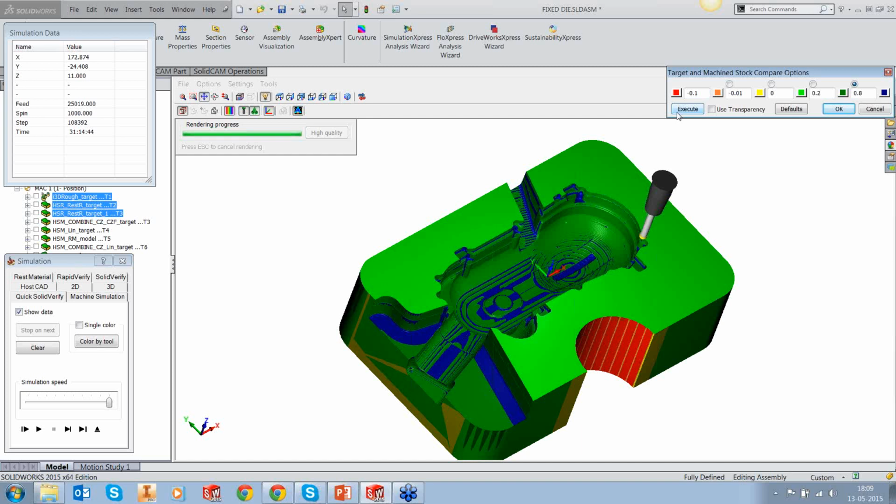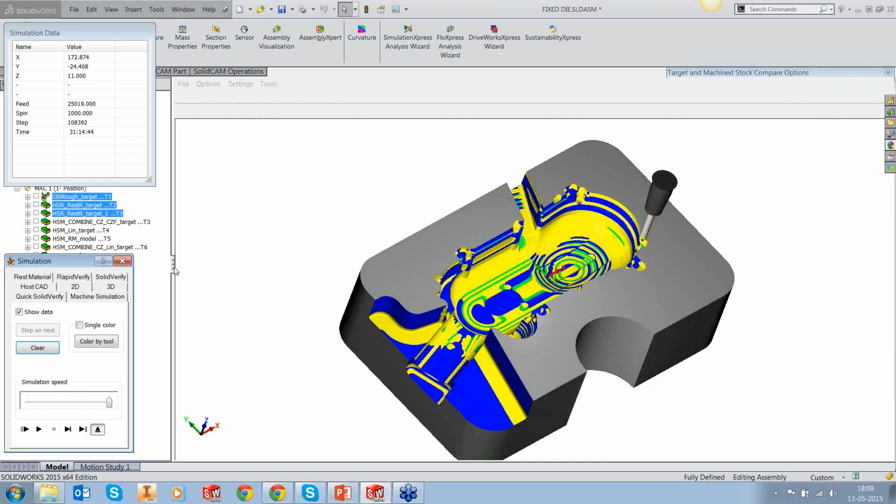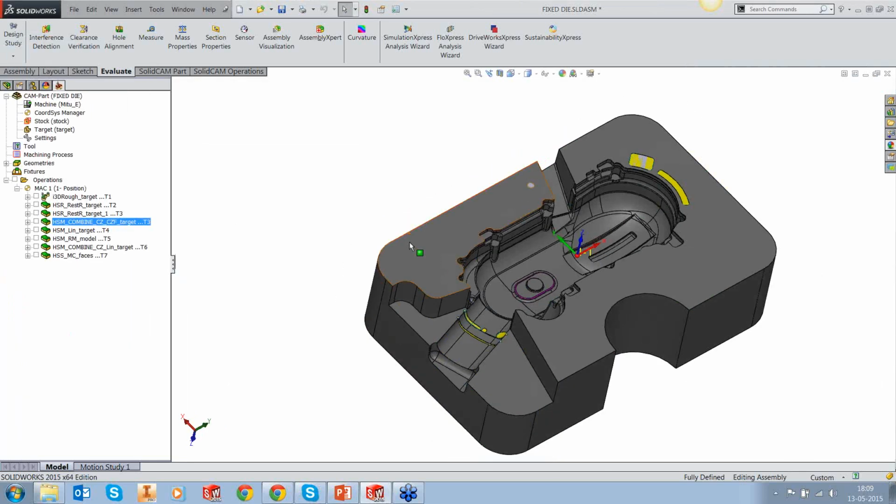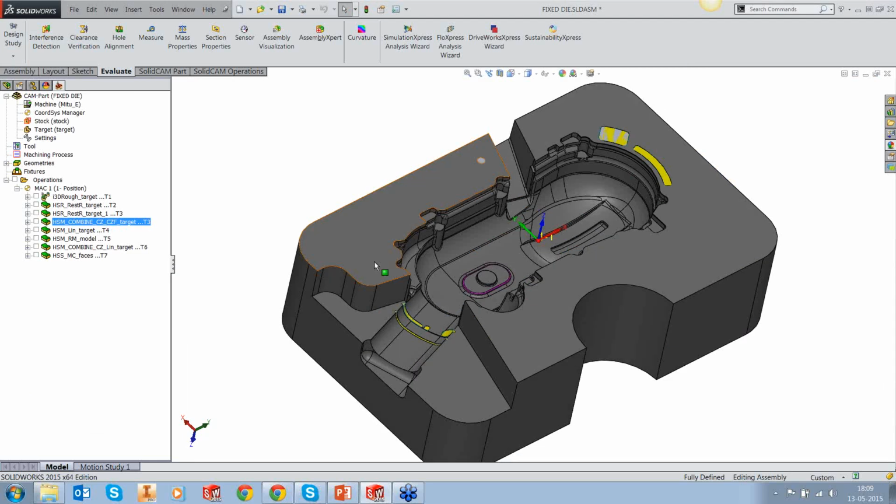So you need to put in a semi-finishing operation. How is that done? The semi-finishing is handled in a different way. The first principle that we use when you're doing semi-finishing of such large parts is to exclude the tool from going onto these near horizontal areas.